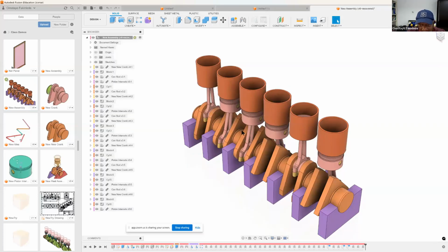So if you look at this, you can see that the crank angles have been implemented. This one is 0. This one is 240. This is 240. This one is supposed to be 600, but when we subtract 360 from there, this one is originally 240. So these two look as if they are the same.